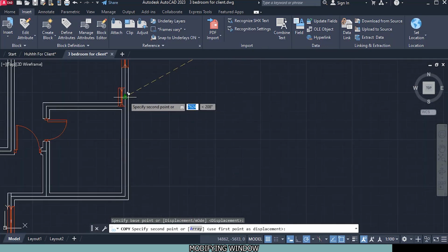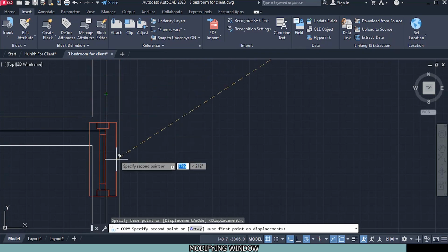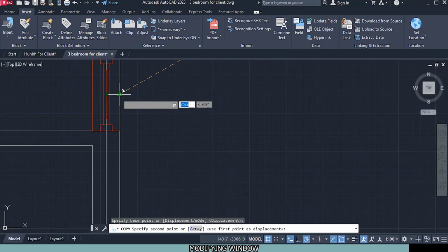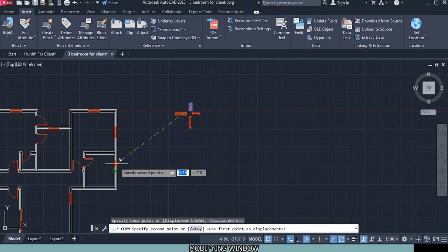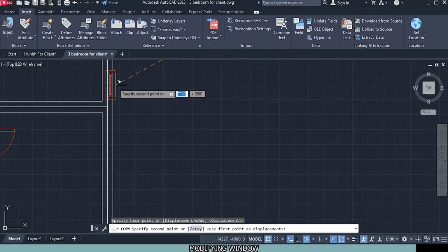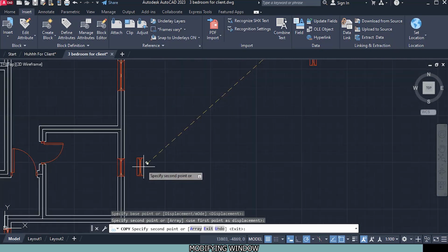It will try to snap elsewhere, so track the outer wall, not the center one. The outer one. So just drag and drag again and zoom out. I'll drag again, just wait, and then place it wherever I want, somewhere in the middle.